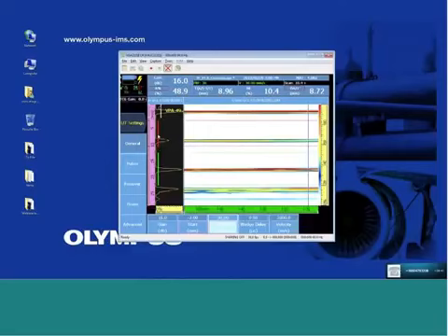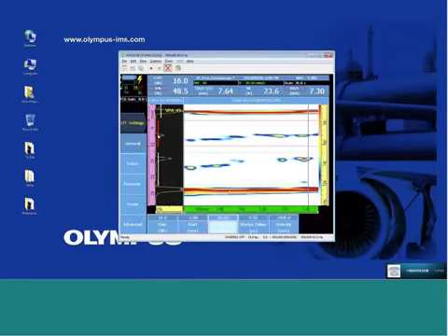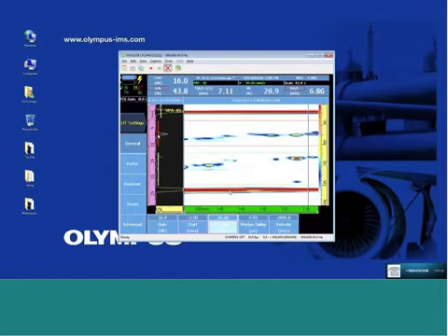The size of your wedge will determine where the wedge echo appears, and the wedge velocity is typically different than the component. So if I remove the wedge from the component and hold the probe freely in the air, I can see that my wedge echo is coming in at about 22 millimeters. So I'm well outside of my range for 2 good back walls. Moving the probe slightly, I can see into the corrosion.